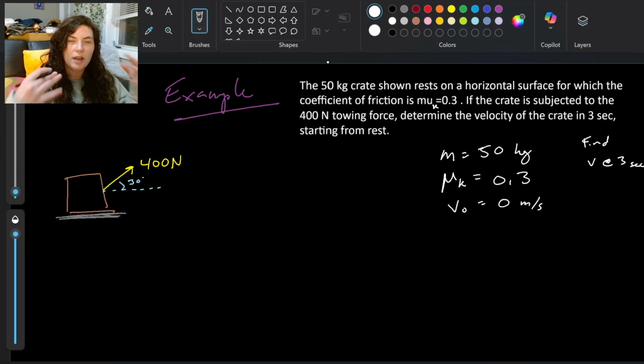So again, the way I want to solve this is to set my coordinate system, draw my free body diagram, draw the kinetic diagram, set up my F equals ma, and do any kinematics I need that's left over to solve. Breaking that down, one, we're going to establish the coordinate system. We already said all of the problems in this video are in the rectangular coordinate system, so it is kind of given to us, but we'll denote that we're working in an xy coordinate system here.